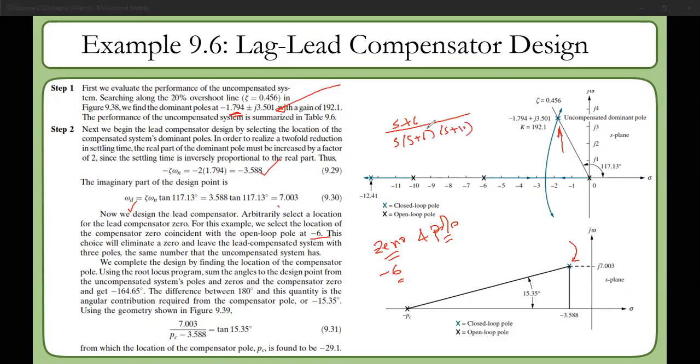So basically, the bottom line is we're cancelling a pole with the zero. We can also choose a zero at the same location as one of the poles, so that we can make it a pure second order approximation. But you have to be careful about the fact that we have another pole that has to be placed, so you have to find the location of that pole.